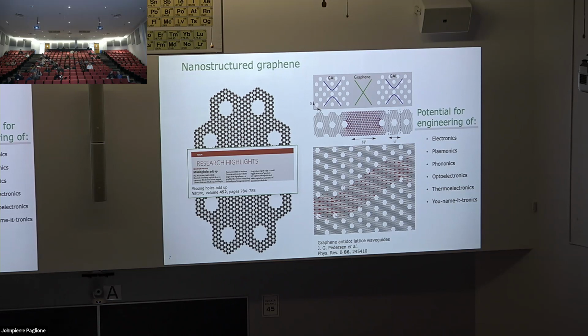Okay, so you put hBN or something on. Exactly. So that's what we ended up doing in the end. I don't think I have that slide in right now, but I have a nice overview of the minimum feature size, like a literature review. The minimum feature size people made in graphene and then mobility. And it just plummets as you make it more and more dense. But hBN is the saving grace, because then all of your processing is done remotely.